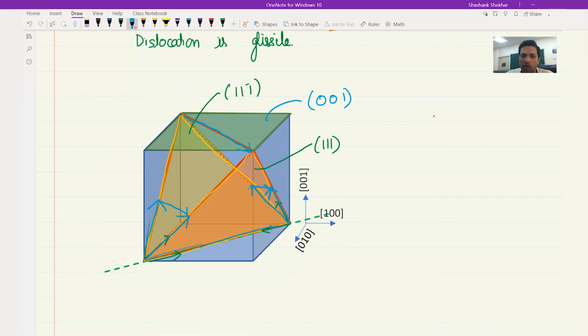So this again gives you an idea that when the stresses are being applied, the dislocations move and they will intersect and interact and react, and this will lead to dislocation multiplication, which is what leads to the hardening of the material. And also the back stresses when there are locks formed like this, or when there is a pileup, all these lead to strain hardening of the material.